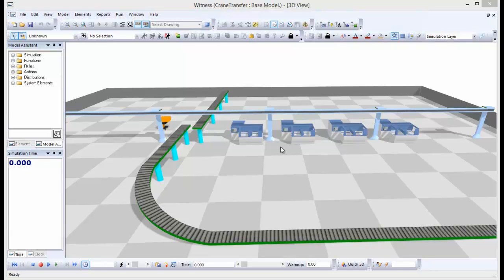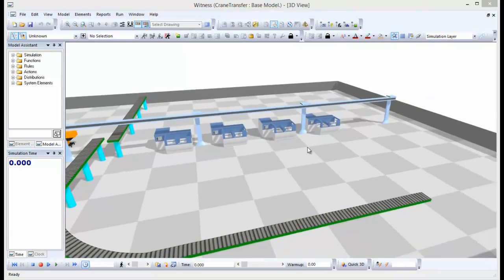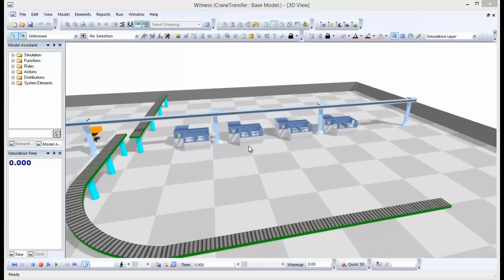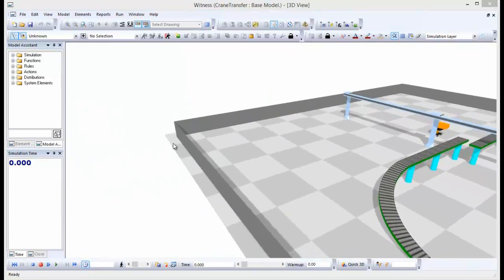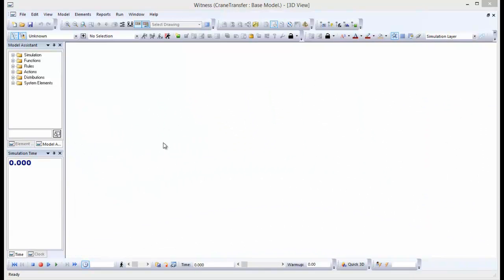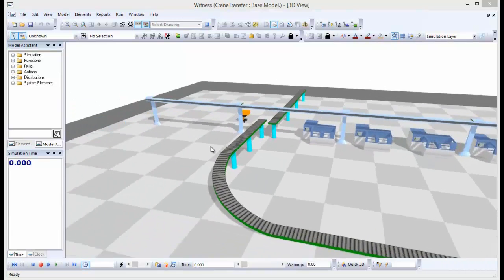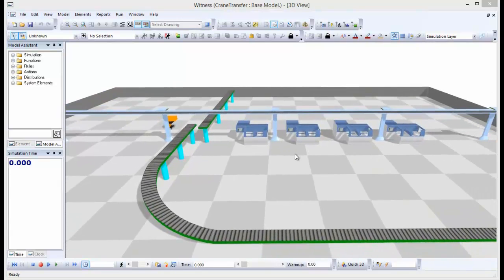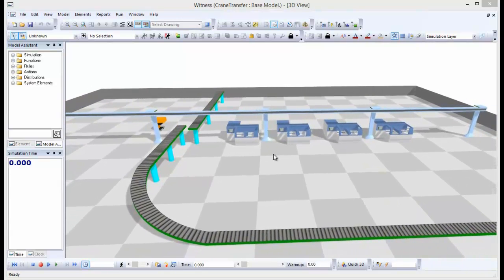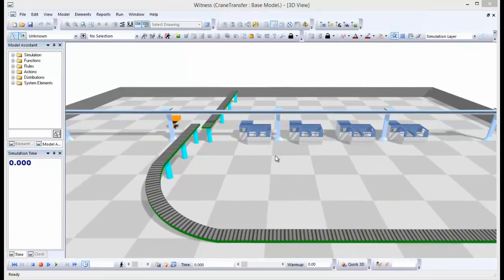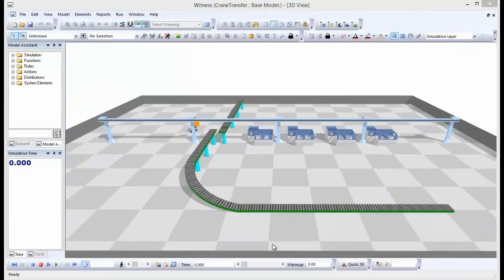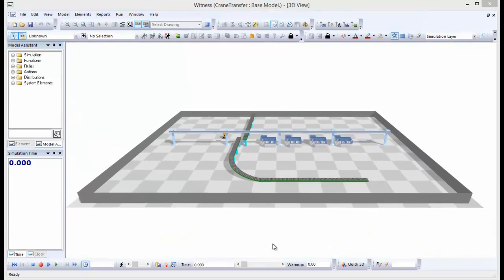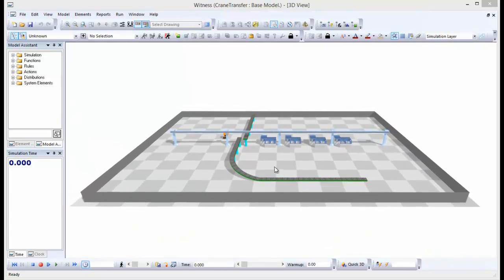Also with the middle mouse button, if I go to the right, we turn to the right, and if I go to the left, we turn to the left. And again, the speed applies, so if I go a long way to the right, we can turn right the way around the view much more quickly. And if I go to the right nice and slowly, we get very fine movement when we're near the center of the view. So I'm going to zoom back out by holding the middle mouse key down again and pulling it back towards me.